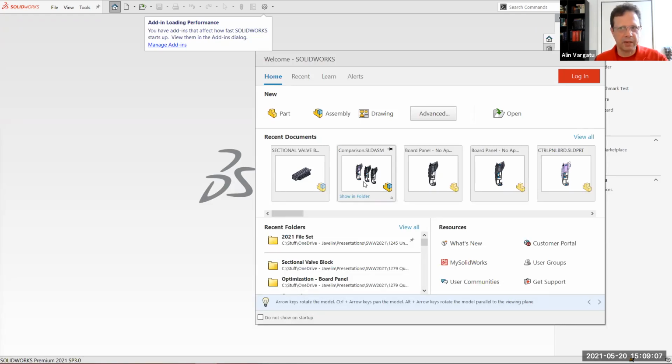And the other thing that I haven't tested yet, but I believe the answer is yes. Even appearances that are being applied to, let's say, bodies and features, if you can stay away from that, it's better. But if you need, just make sure you don't apply appearances to faces. Try to apply to everything that's higher up the list, like the whole part or a whole body, or if you need a whole feature, instead of going face, face, face, face, face.